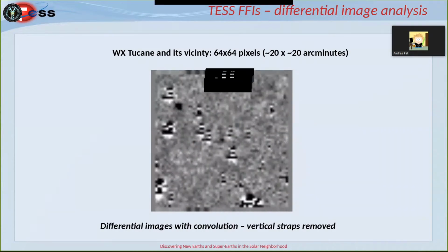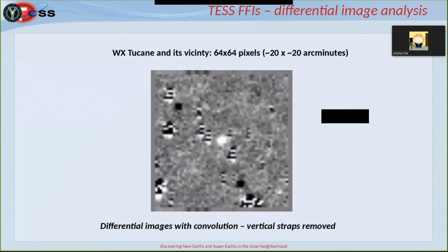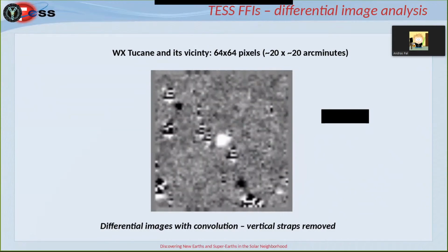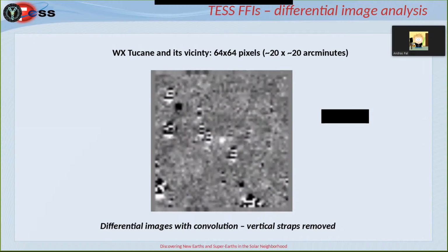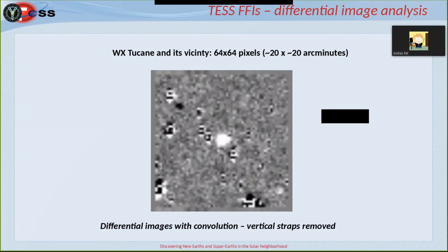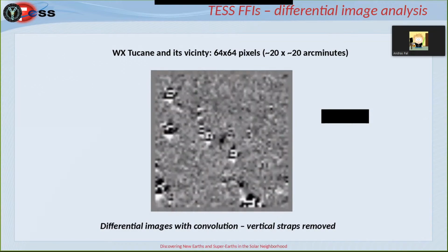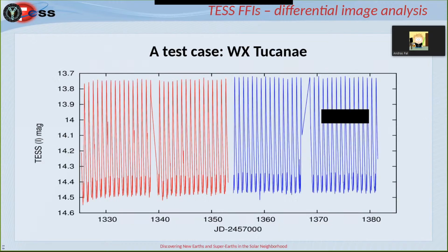So basically, it's also Earthshine, but amplified by the detector a little bit. It's a side effect of the manufacturing process of the CCD, which has, of course, many advantages, because the gain is very high and the charge transfer efficiency is very close to unity, so the CCDs are very good at the cost of these vertical straps.